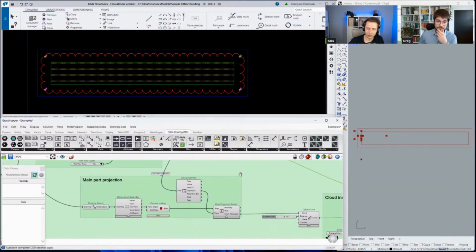So you tell me right now, if I have 100 drawings in my Tekla model, and in all of them I have to give a revision cloud for every single part. Let's say I find one beam, so I can go through 100 drawings and give the same cloud for every single element, and give even the revision name and so on for the UDAs. Yes, but you need to be able to filter them. So that's of course yes. If you find the right beam for every single object, I know the rules, but I just want to tell the principles, like a big project, and I have this kind of task, so it sounds really amazing.